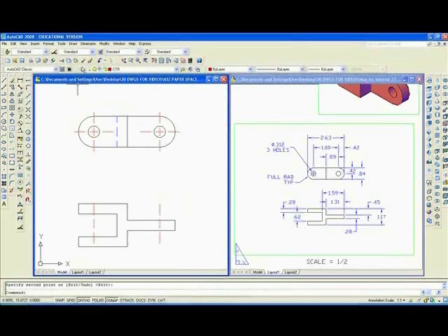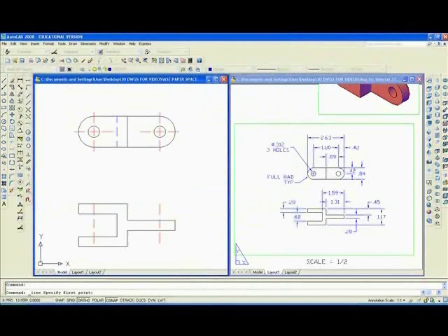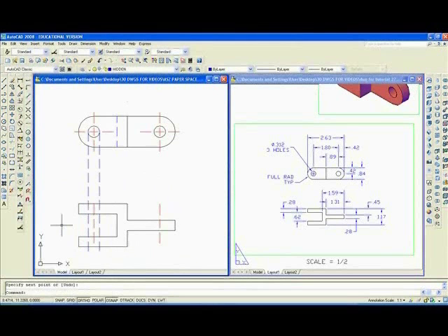Also, we might want to make the hidden line current, and we can draw a line from the quadrant down here like that, and another one from the quadrant on the other side like that. And we can break anywhere at these 2 points, and then we can trim from all 4 lines the excesses. Try it again. Trim. Enter.